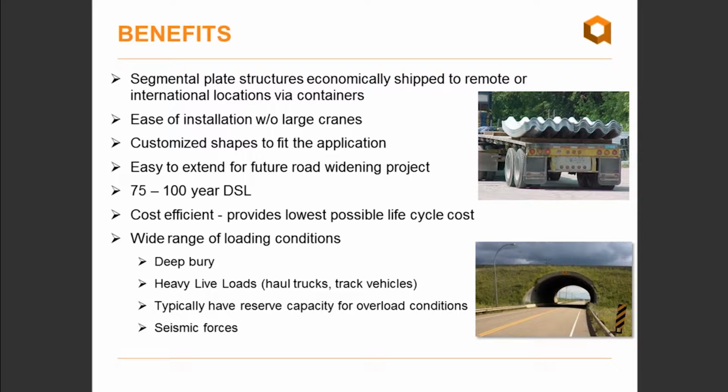With some of the recent developments in coating options and design for durability, these structures can easily provide a design service life of 75 and in some cases 100 years. Material options within a certain span range, as such, they can provide the lowest life cycle cost in that span range. And because of their flexible nature, they're well suited for a wide range of loading conditions. This relies on the fact that these structures can flex to shed loading on the surrounding backfill envelope. So from deep bury or high fill situations to heavy haul truck loading in mining applications, these structures can accommodate significant dead and live loads.